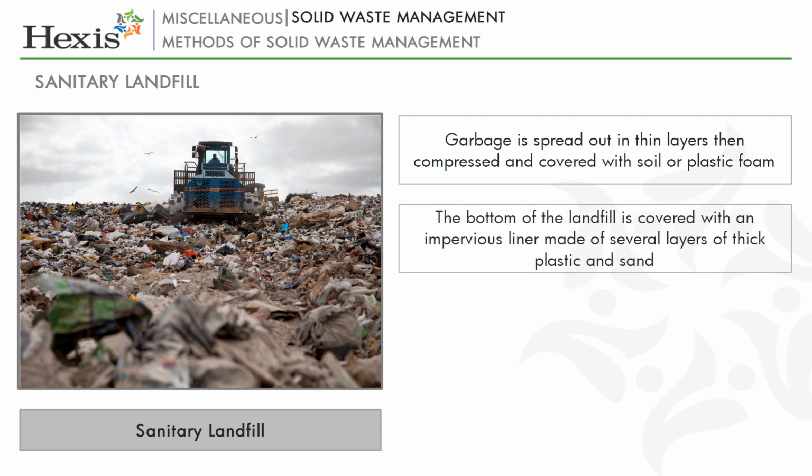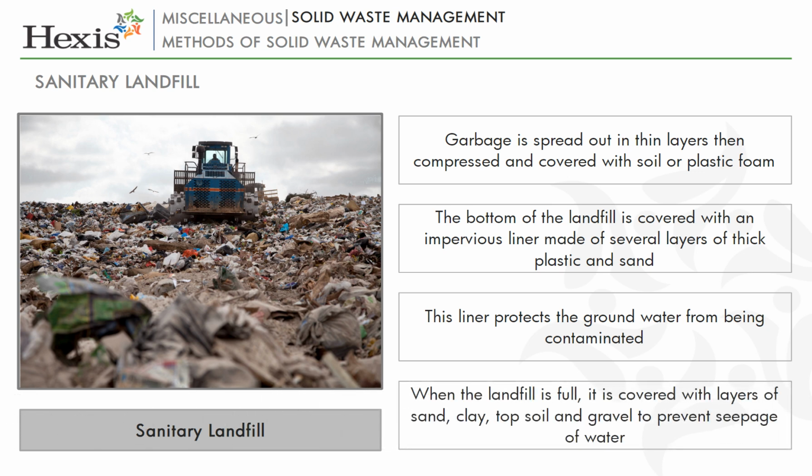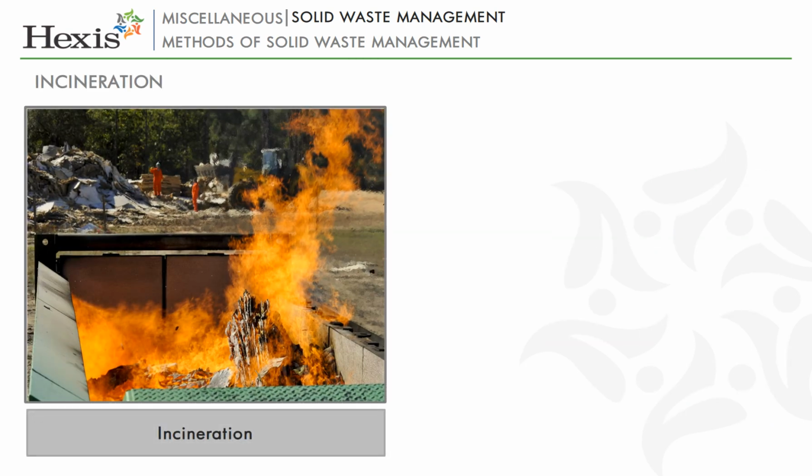Modern landfills are designed in such a way that the bottom of the landfill is covered with an impervious liner, which is usually made of several layers of thick plastic and sand. This liner protects the groundwater from being contaminated because of leaching or percolation. When the landfill is full, it is covered with layers of sand, clay, topsoil and gravel to prevent seepage of water.